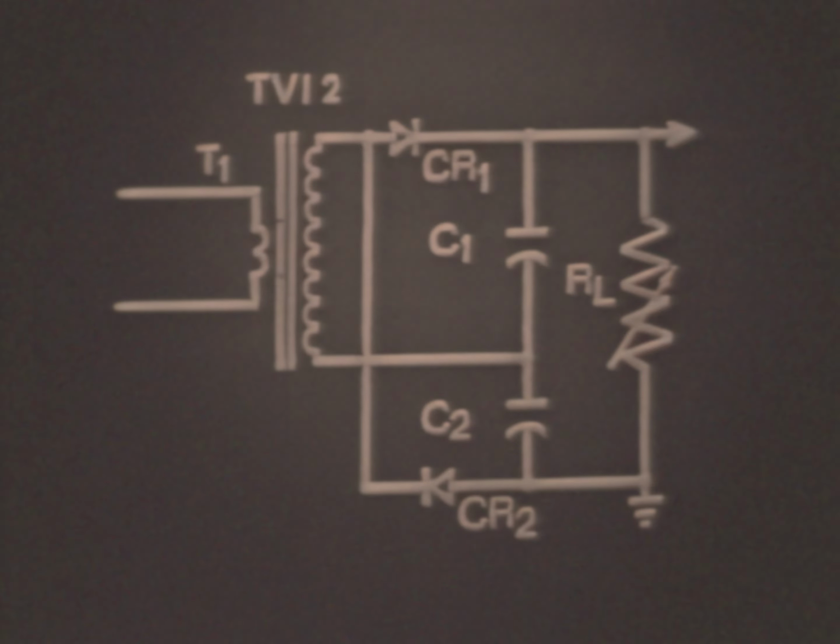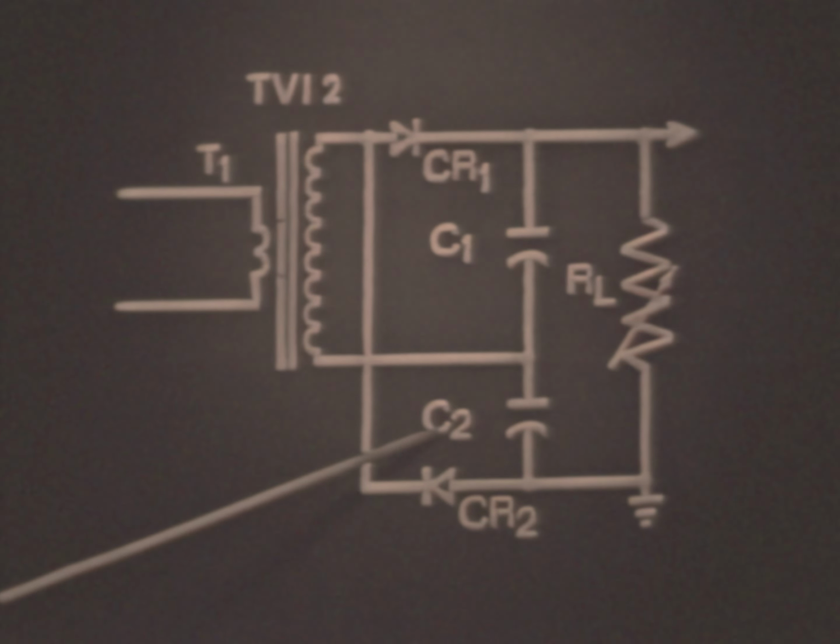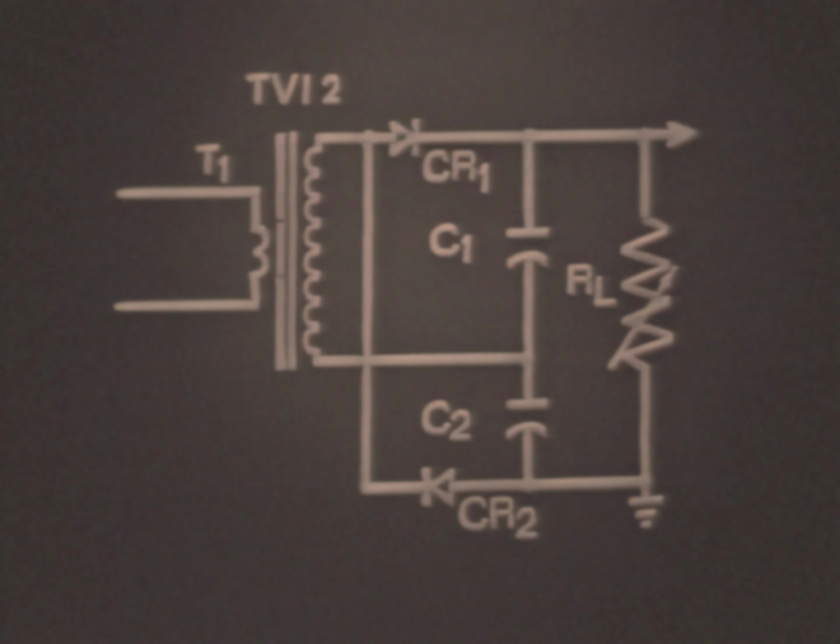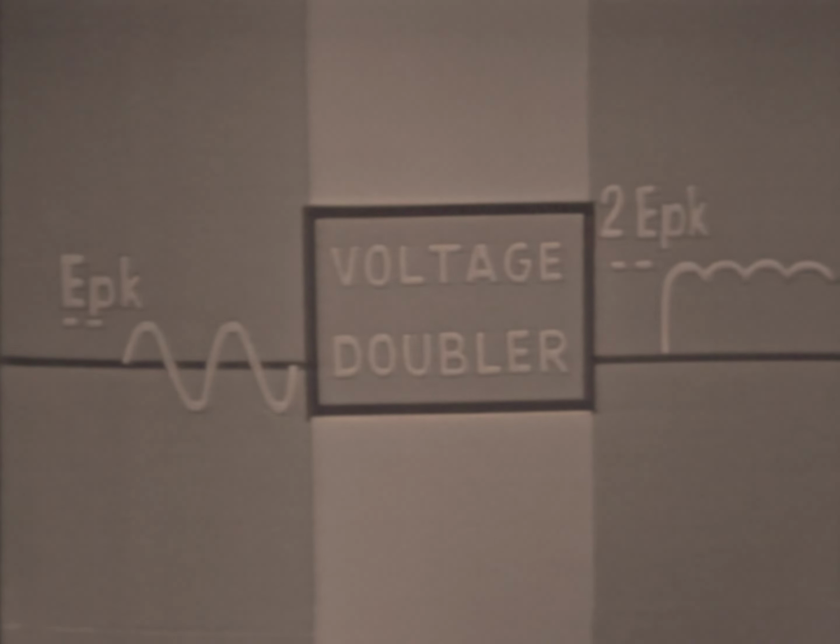The reason is that the output voltage is developed across C1 and C2 in series. Also important in the voltage doubler circuit that we discussed is the output ripple frequency, which we learned was twice that of the input frequency. And the reason it's twice the input frequency is because the voltage doubler used full wave rectifying action, thereby developing an output pulse on both the positive and negative alternations of the input signal.